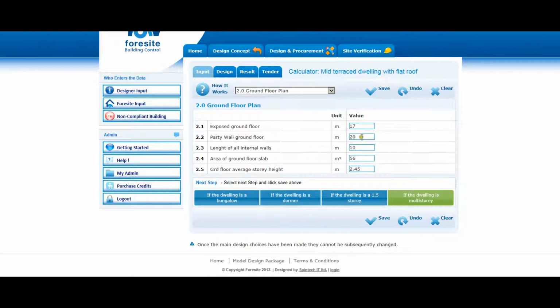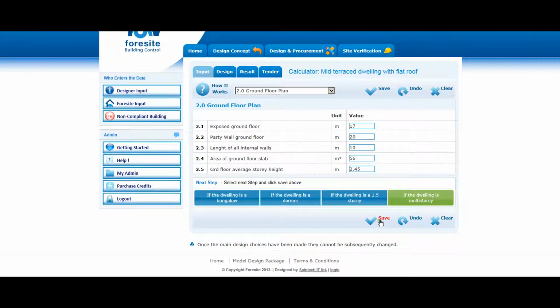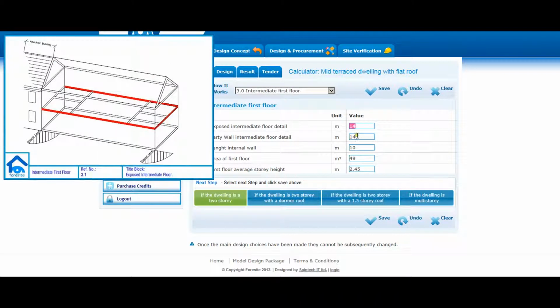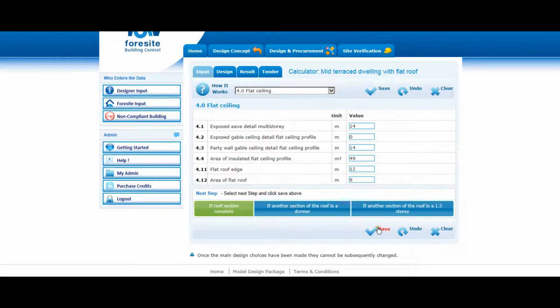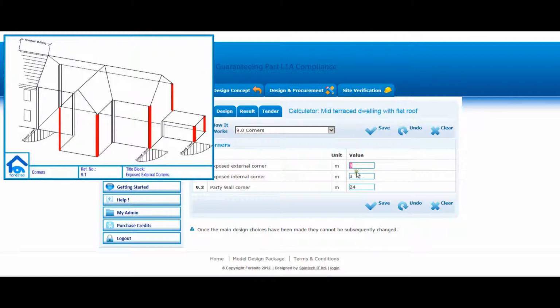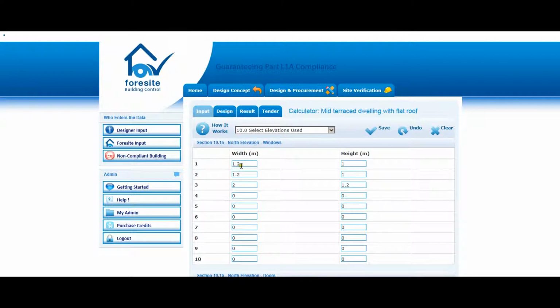As you can see, there are a lot of construction joints with this type of dwelling. The extension means that there are more exposed areas than a normal mid-terrace building. The exposed wall on roof areas and construction details makes design compliance difficult to achieve. We have more construction details. This project has 3 exposed elevations and there is a small volume with these dwellings. Compliance is also made difficult by contemporary design, which has a lot of glass, and this can cause overheating.